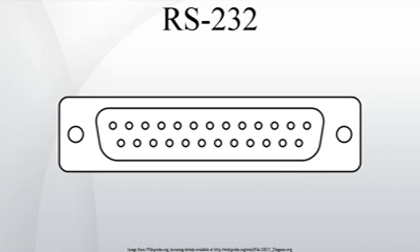The standard does not define such elements as a character encoding or the framing of characters, or error detection protocols. Details of character format and transmission bitrate are controlled by the serial port hardware, often a single integrated circuit called the UART that converts data from parallel to asynchronous start-stop serial form.